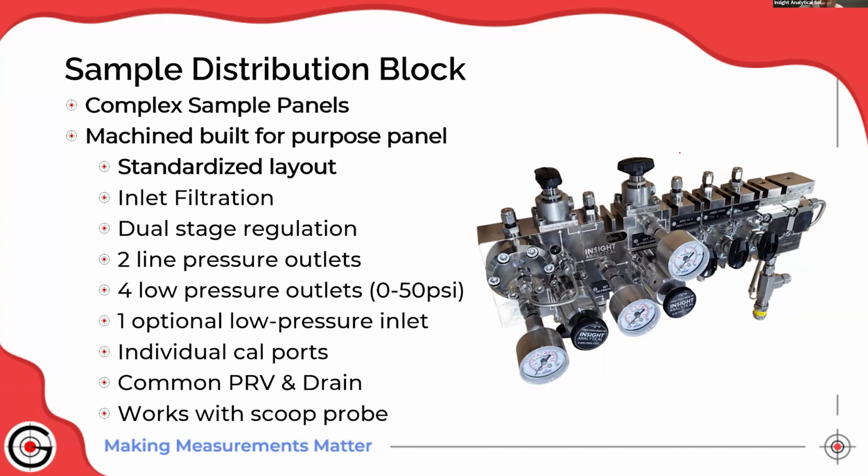All these fittings on the sides, we tend to try to avoid NPT fittings. We use straight threads with O-rings. They seal better, they don't gall. So very maintainable in the field. Small, compact, takes up way less wall space. And we can apply this to natural gas metering applications, to SEMS applications, any place where we're using multiple analyzers.